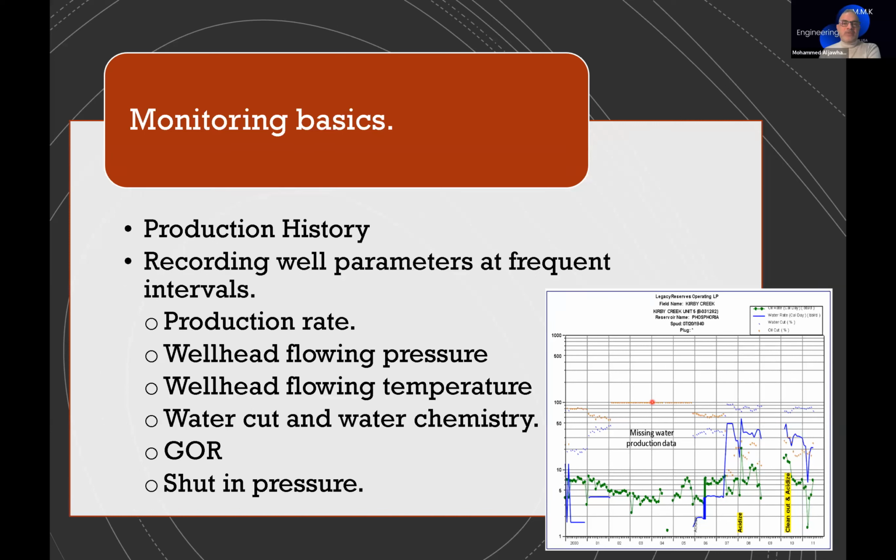If we have a problem, for example, if we're focusing on this part, we can do acidizing because we've suddenly seen a decrease in well production rate. So after monitoring the performance of the well, we think this is the remedial action we need to take, and see whether there is a good indication of this acidizing helping the well go back to its original production rate.